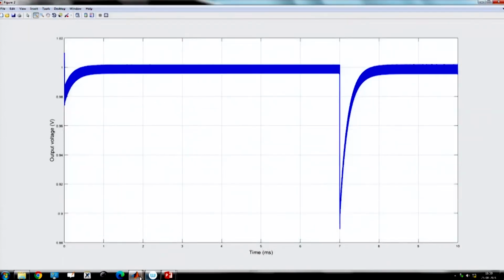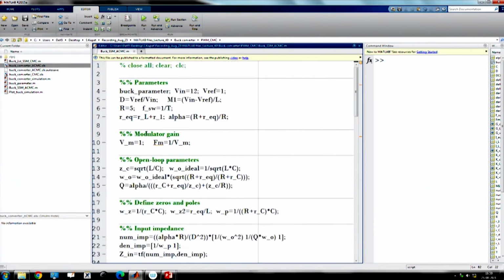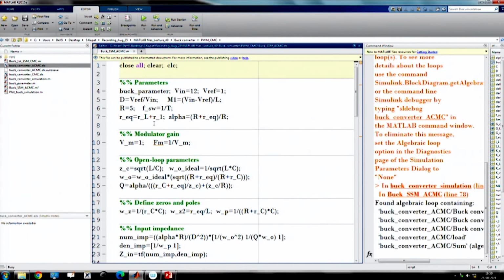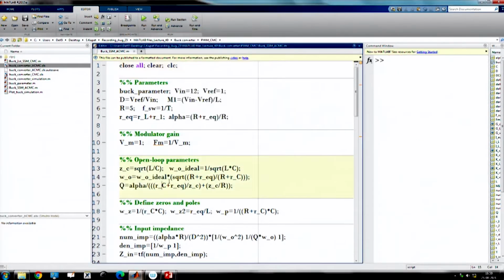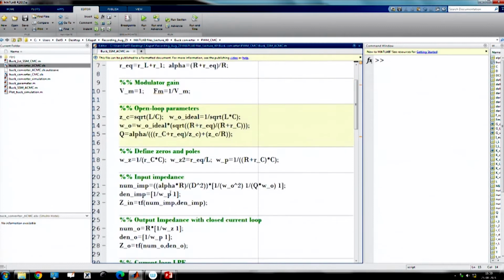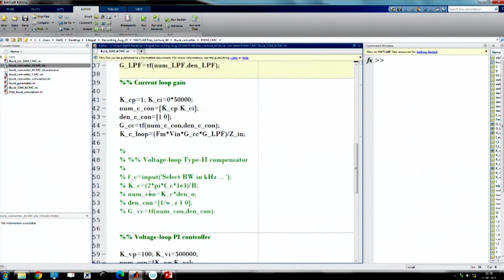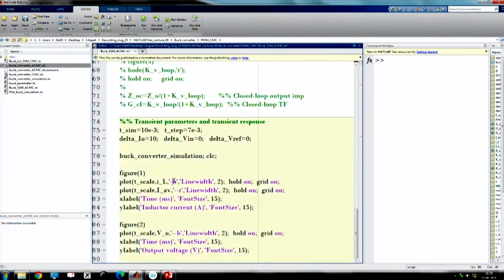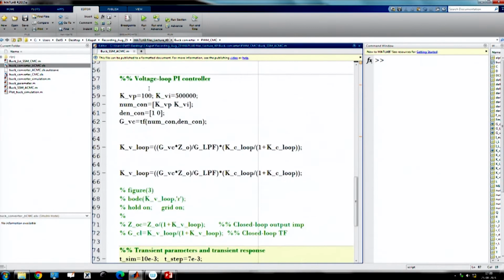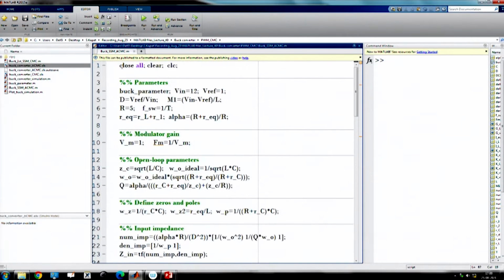Now, we want to repeat this experiment, that means instead of putting multiple waveforms, we want to run the same waveform here. Now, it is the dotted line, okay, and now we want to further reduce the current loop low pass filter bandwidth to, let us say, 2 times. Now we are using solid line, and we want to plot one over the other.